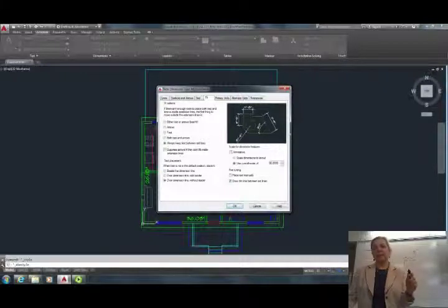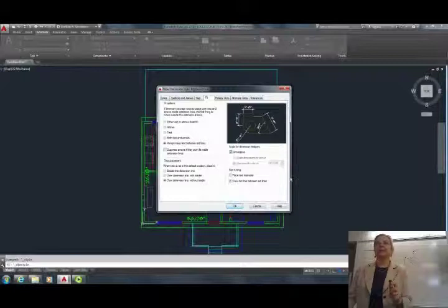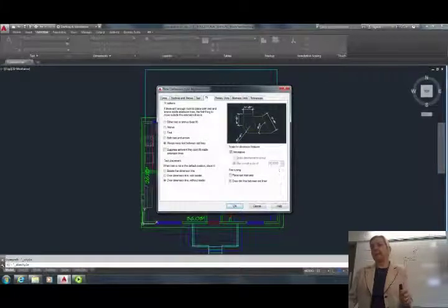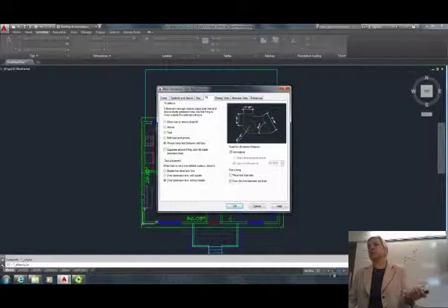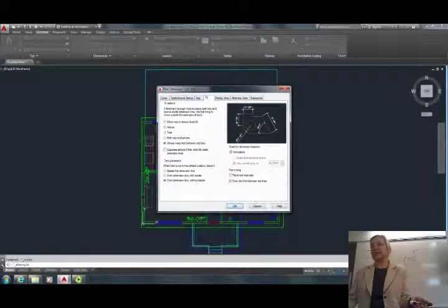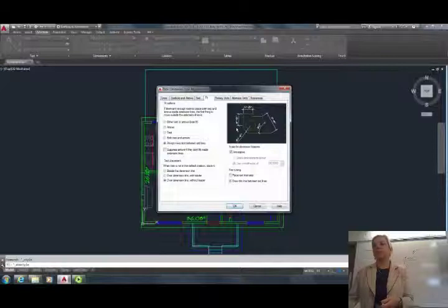Okay, and here are the two ways you can do your drawings. One is annotative, and then the scale here will be taken from the viewport. Within the viewport, and this is something that you must remember, if you go annotative, then you have to have these functions on, and you have to set the scale in your viewport. It's not showing now because we're in the model space. But you have to set the scale you will be printing at, and then as you change that scale, the sizes of everything that you're specifying here will be going up or down per the viewport scale that you're assigning here.